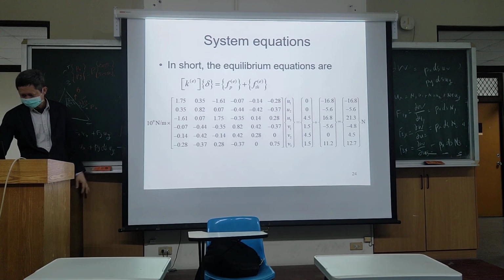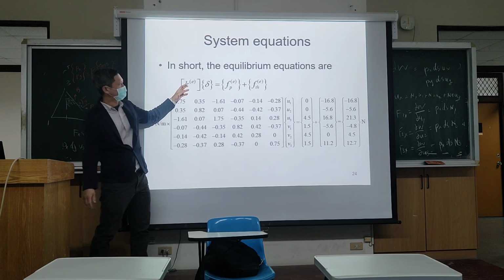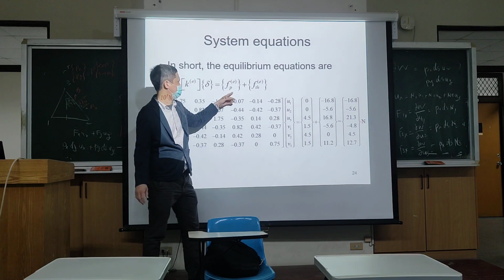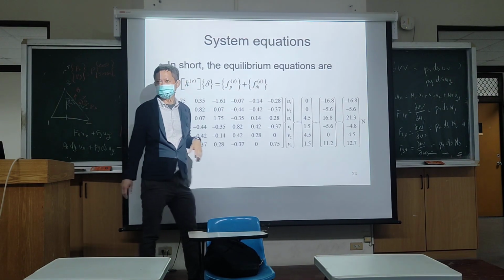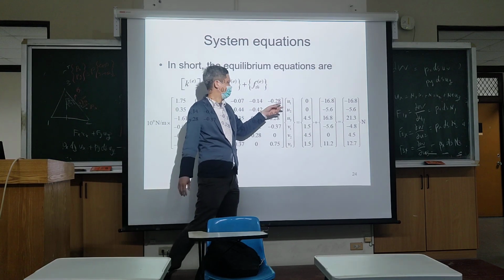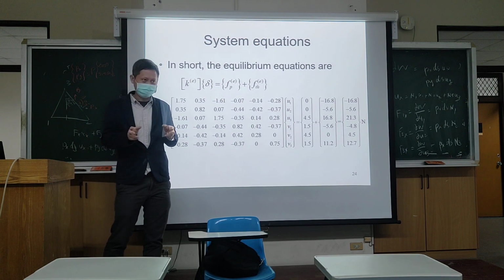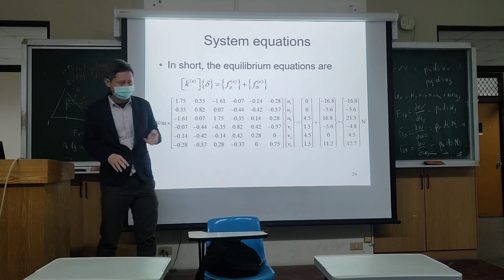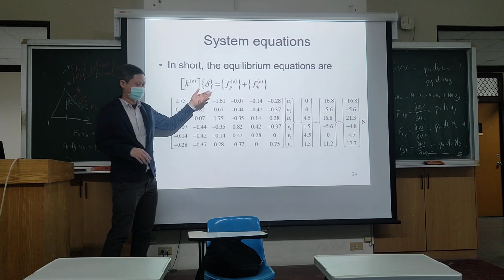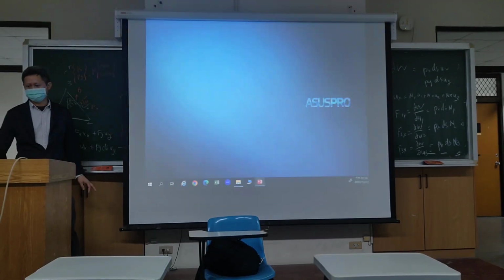So in short, now you have the elastic force in balance with pressure-induced force and the thermally induced force. Okay? So now you can find out how much is your displacement. Here displacement must be an accumulation of all strain, elastic strain and thermally induced strain. So that's the total displacement. So in that way, you finally do the solved solution.